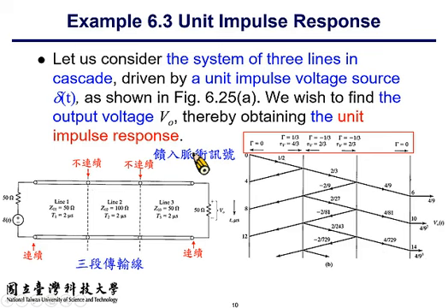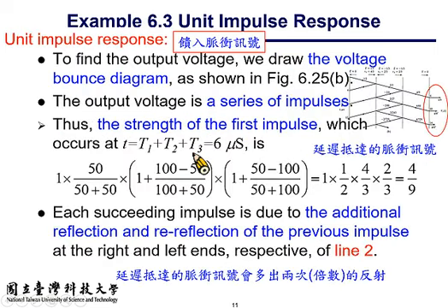It is 0. And so is it for the signal going into the source, so the reflection coefficient on the left-hand side is 0 as well. So before proceeding to draw the bouncing diagram, you need to calculate the corresponding reflection and transmission coefficients at the interfaces and terminations, right?